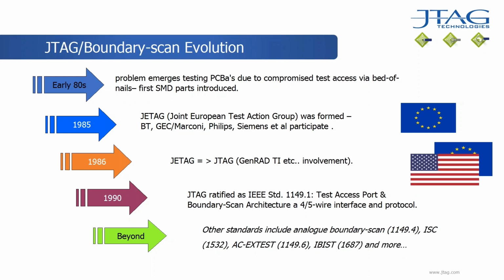Wave flow soldering was quite reliable, and in-circuit testing was used to probe the pins of the through-hole components in order to test their functionality and also to test the connectivity between them. But as surface mount devices became more prevalent, the bed of nails technique became more difficult to implement, and so some people sat down and worked out a method of embedding test logic into devices so that it could be used in place of the nails.